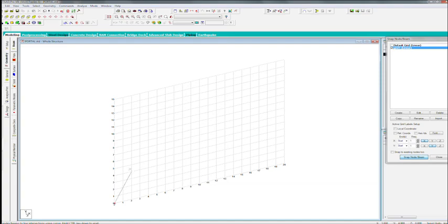And you see we're drawing our members, and if you notice over here on the lower right corner, it'll tell us the coordinates where we are at any point. So going to the top, we can see now we're at 15 in y. We'll scoot across, and we'll be at 20 now in x, so this would be 20, 15, and then drop on down to 0, so we're 20, 0.